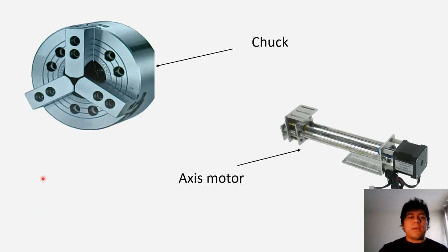We also have the chuck. The chuck will be holding on the spindle, and so remember, just a quick review, of course, from the lathe machine. The chuck works to hold one end of the material very, very tight. As you can see here, the chuck has 3 teeth on it. There are some that have like 4, others that have 6. Of course, it depends on the diameter and the brittleness of the material as well, and also the hardness.